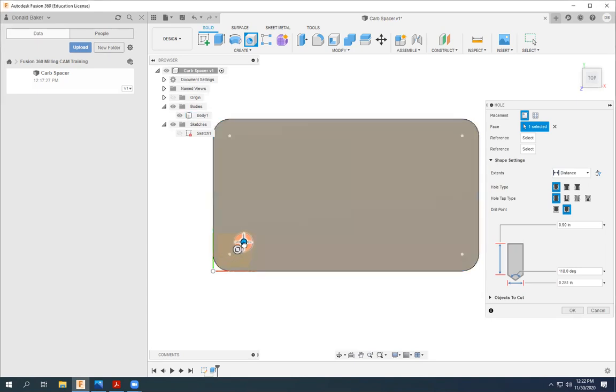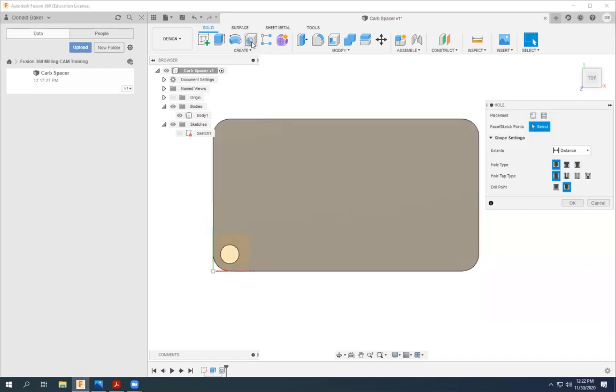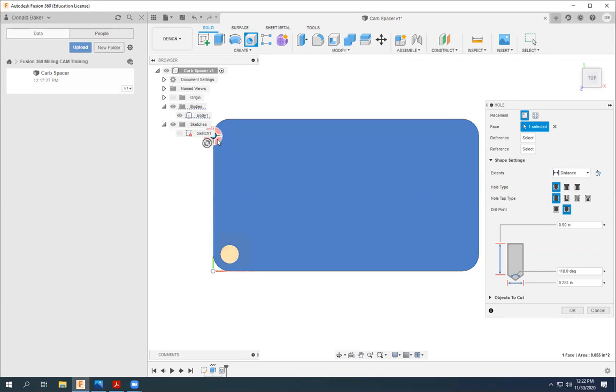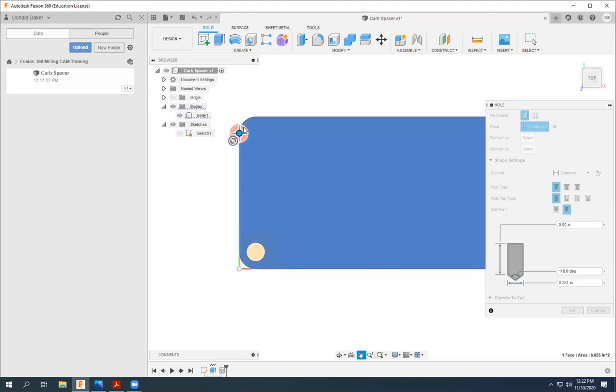And the next thing we want to do, since we're using the same arc centers to be concentric with the arc centers, is just to be able to snap to that little white dot that Fusion shows us. And at that point, we can just go ahead and click enter, and then I'll finish making our hole. So go ahead and quickly make more of those holes by just go ahead and click approximately where that hole should be. And then moving that center point.